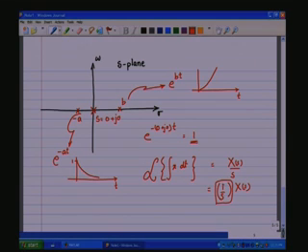Of course, here the numerator is just 1, and the denominator has an s value there, and therefore it can be 0. That is, this function has a root of the denominator at s equal to 0, and that is a pole. So, at the pole value, when you substitute s as 0, the gain is infinite. The gain of the function between the input and the output becomes infinite.